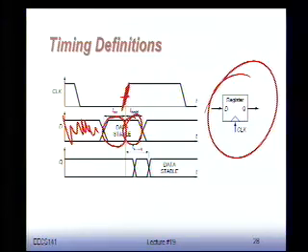Okay? So setup and hold times are very important properties of a flip-flop as well. And violations against those can be not very healthy for you. So if you look at most companies doing complex design with a lot of designers, there are going to be automatic tools that check and verify that you don't violate setup and hold times. It's one of the biggest violations that can make timing go wrong in the design, the violation of this setup and hold time.